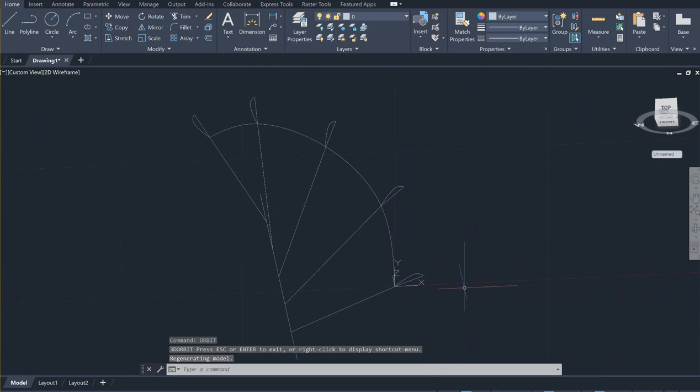So at this point, we're applying a number of commands available. One of them is the loft command. For example, loft works through cross sections. Let's go with the loft command and see how we're going to get this. Loft cross sections in lofting order. Okay. And the mode gives the option of solid mode, enter.